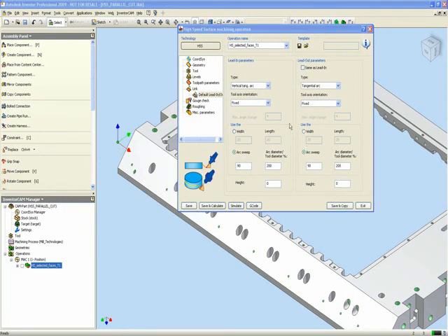Now we also have control over how big of an arc we want. We can have it go in from a complete 90-degree angle or change that if we want. As for the arc diameter itself, we can have it as a percentage of the tool. Right now it's 200% of the tool. So if I have, for example, a 10 millimeter diameter tool, and I have this at 200%, the arc that it will go in at will be a 20 millimeter arc.